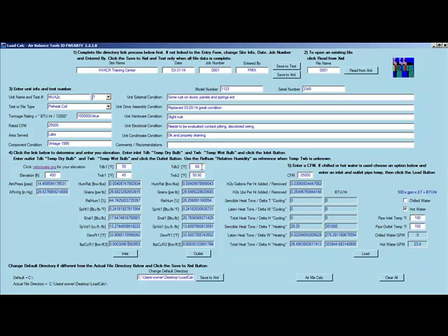Now our outlet temperature is going to be 68 degrees. We know that if we're just increasing or decreasing sensible heat, we're not changing our grains. It's a straight line. So we want to make sure that we match our grains, and we can do that by just changing the number to whatever you want.